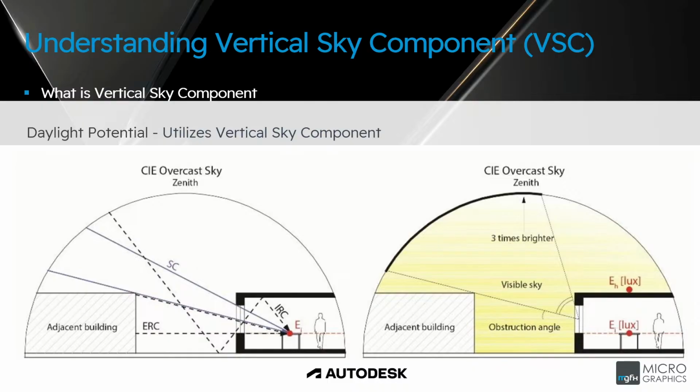Daylight factor uses knowledge of window details and material reflective properties to measure direct and reflective light coming in through windows and potentially being reflected indoors. However, direct light from the sky through a window is typically the main contributing factor to a DF score.